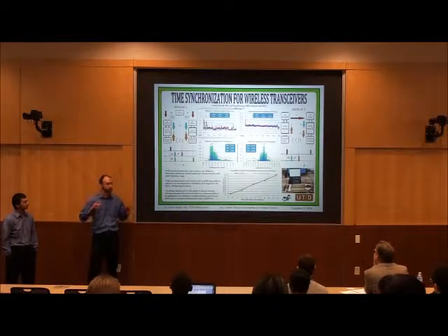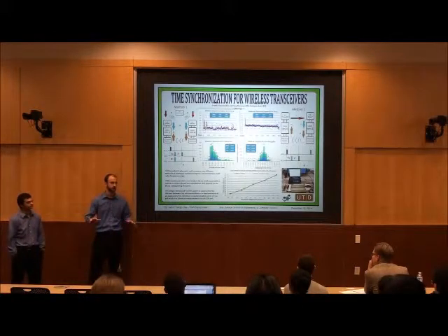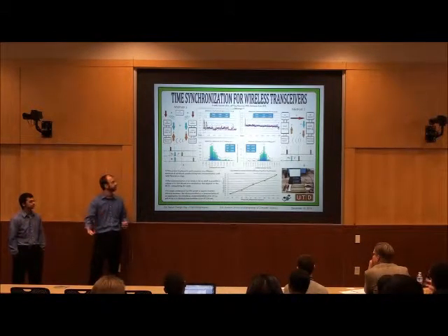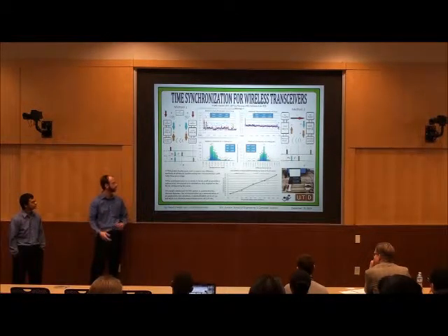Basically, for our project, we designed and implemented two methods to wirelessly synchronize two separate microcontrollers using radio frequency beams. To synchronize, what that basically means is we want these two separate microcontrollers, these little computers, to be operating on the same time so that we can have a common time reference from which to do calculations. Our application was the ultrasound distance finder using the time of flight principle.